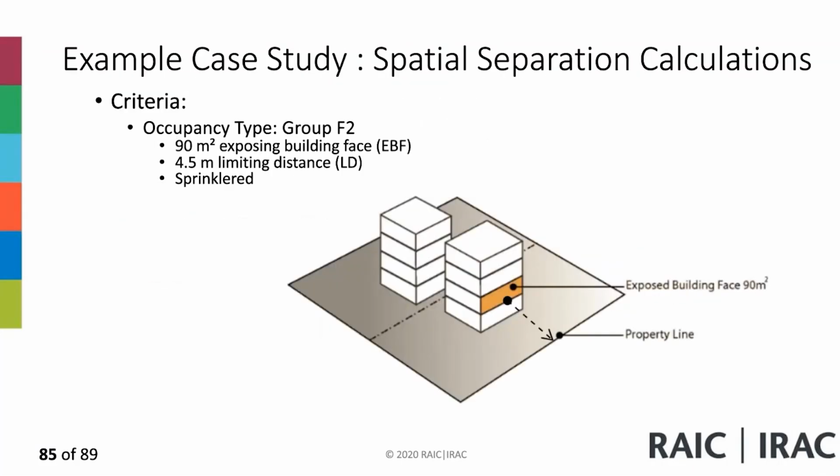Do you measure from the center line to the other center line of the other column or other wall, or do you take the measurements from the inside face of each column or wall in order to get the area of exposed face? Okay, so no, it's not the inside area, it's from the center line to center line. It's about the exterior wall. It's not the interior portion of the wall.